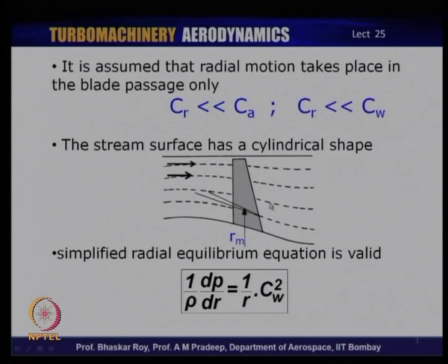And this equilibrium of forces, if it is adhered to or invoked in the design of the axial flow turbines, then each of those passages would have a radial balance of forces, and then it will be only due to this opening up of the passage, which means near the tips, for example, in this particular shape it would be quite flat.